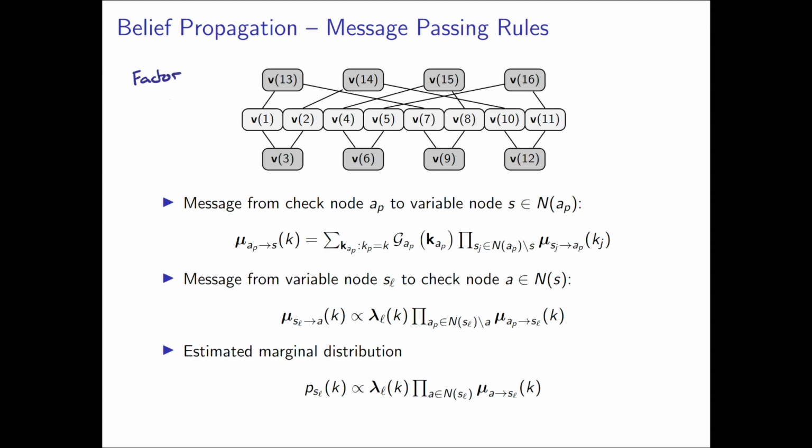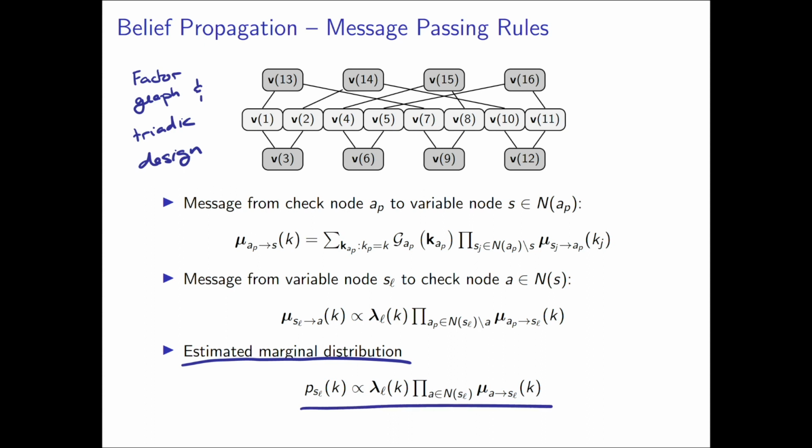Again, once we've settled on the structure of the outer code and some approximations, the message passing rules are somewhat standard. We note that belief propagation also gives an estimate about the probability that a particular entry within a section is non-zero. For our implementation, this estimate is given by this expression. This represents the belief that a particular device has a 1 at index location k within section L. This slide summarizes how we use the outer code within one AMP iteration.